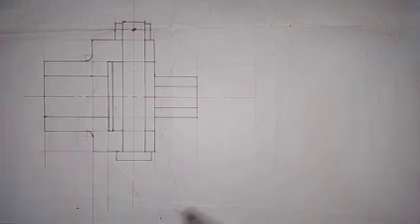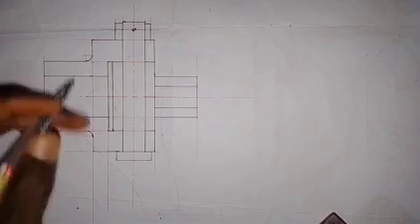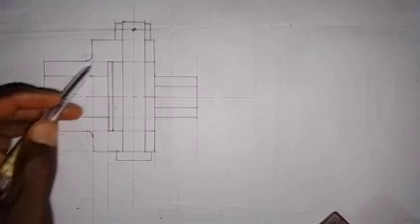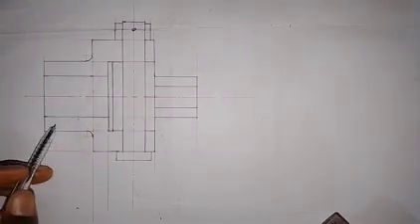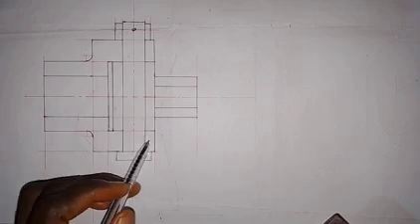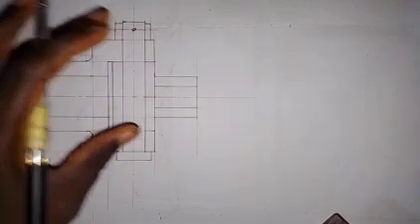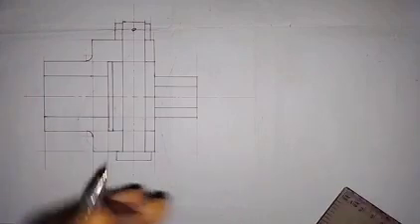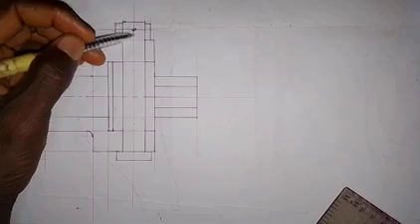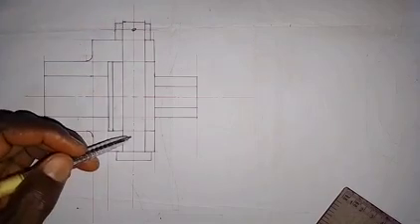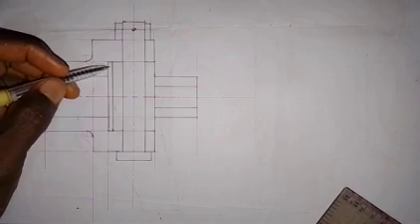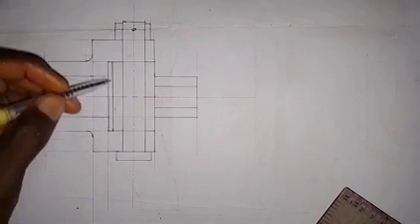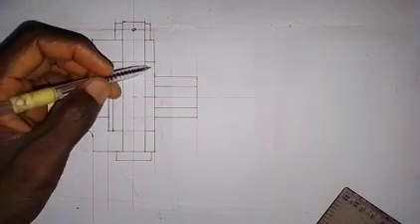So now, having assembled the part together, the next thing we are going to do is to hatch the part that we are going to see hatched, the solid part. So this is solid part, all to here. And for this one, we have this to be solid part. Don't forget that we have different components that we assemble together. We are not going to hatch this pin. This one we are not going to hatch either. This is just a plain surface. We are not hatching it, but we are hatching this part, this, and this.